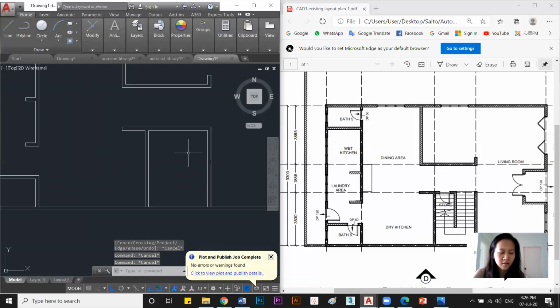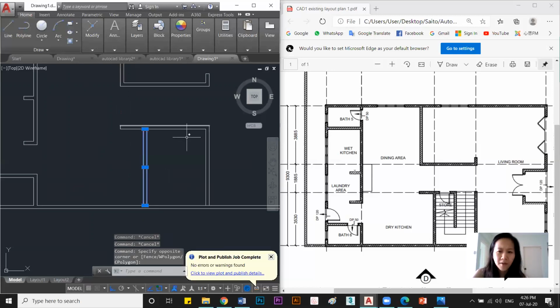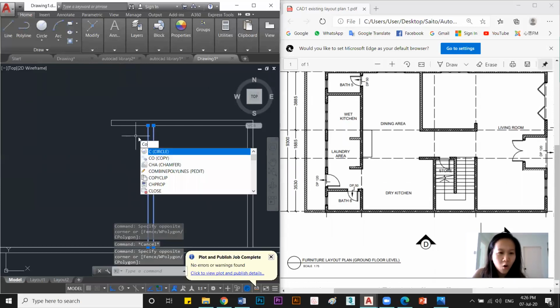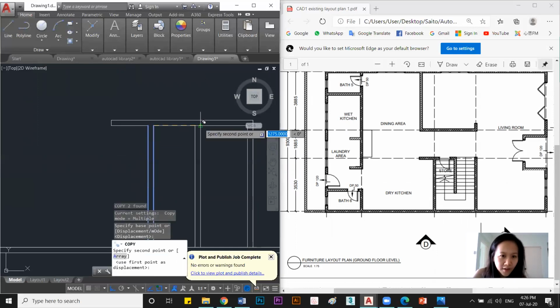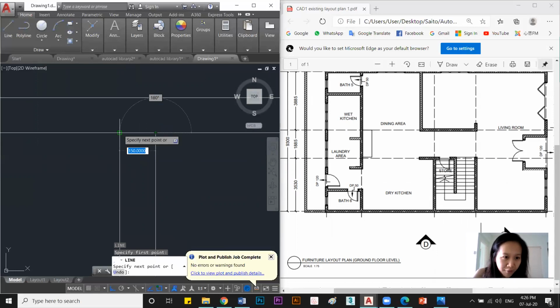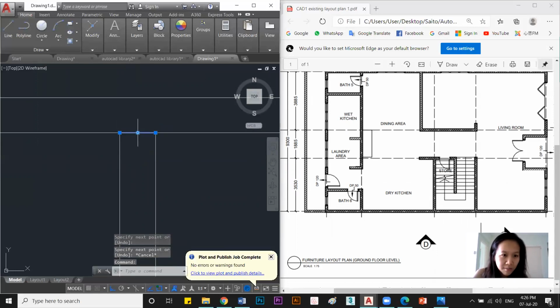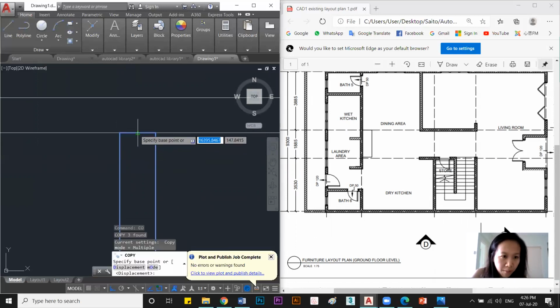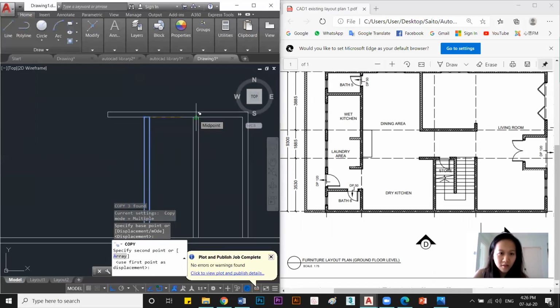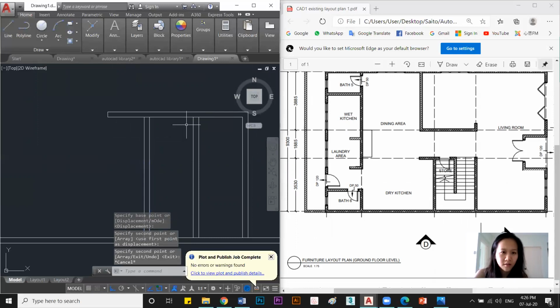All right, and then copy the middle wall for the stairs. This one. CO, copy. Go to find the midpoint. Wait, let me draw another line here so that I can find the midpoint. Okay, that's the midpoint here. I copy this, CO copy, and move from the midpoint, the triangle midpoint, to the midpoint here. You see the midpoint, okay? Then only I delete,